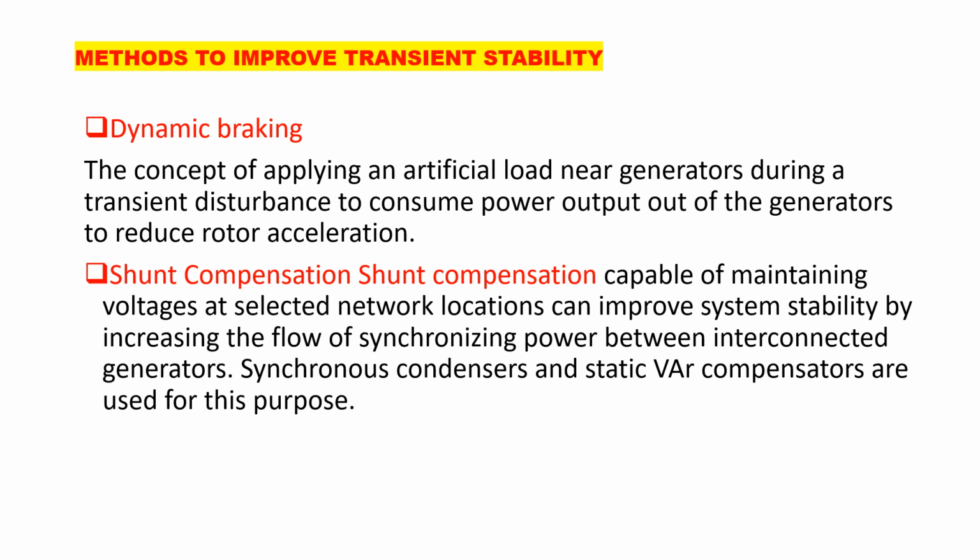Now there is one concept of dynamic braking, where you install some artificial kind of loads on the generator and you reduce the rotor acceleration. Here come those lectures; you can go through my lecture where I explained very clearly the acceleration and deceleration of the generator and the increment in the rotor angle due to the rejection of the load or the addition of the load abruptly on the power system due to the tripping at various points in the power system.